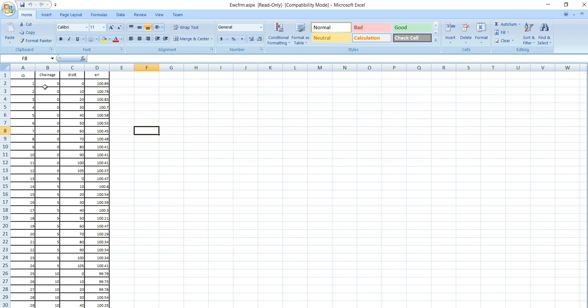So here is the chainage column. This is chainage 0, the first chainage, and we are taking so many locations, that is 0 distance and 10 meter distance, 20 meter distance, 30 meter, like that, according to the area you have, and you can have 70, 80, 90, 100, like that. So these are the existing ORLs, and like that, the next chainage, the 5th meter chainage, again distance-wise 0, 10, 20 meter, you take the initial levels, like that.